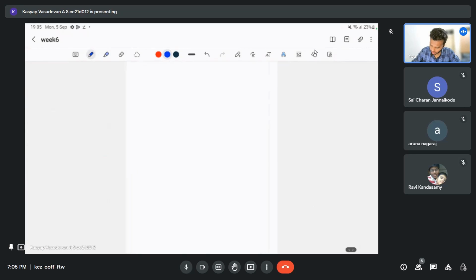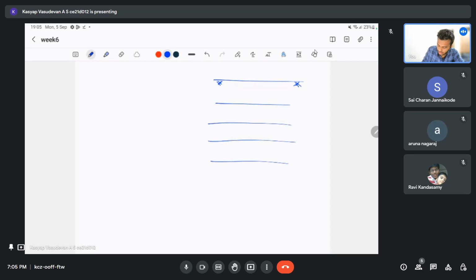So I would like to add one more point. That is that here till now, what will happen if we have multiple layers? So let us say we have a layered surface. We already entered layered actually because we consider the two, above water table and below water table, as layered. So what if we have layered soil with different phi values and different cohesion or whatever different values? So we can divide. What if our pile is like this?